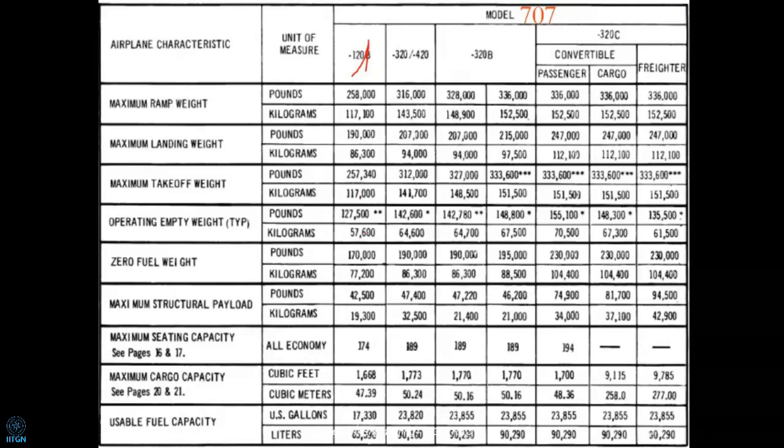And when you talk of extra fuel, the fuel is required for the journey. By law, by ICAO law actually, International Civil Aviation Organization, they have to carry enough fuel, not only from, let us say, Delhi to Calcutta, but also if by some chance you can't land in Calcutta, the nearest airport, maybe Bagdogra or some other place. So it has to have the trip fuel from Delhi to Calcutta, and then extra fuel to land at some nearby airport if it can't land properly at Calcutta. So all that has to be carried by the aircraft.